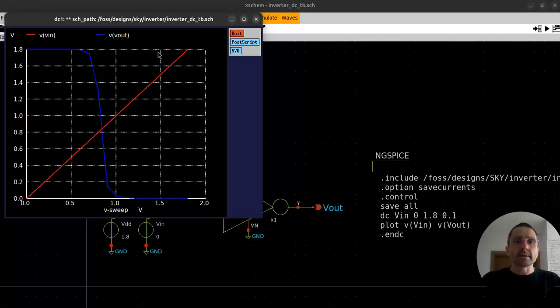And we were able to simulate this new netlist, although there was an issue, because the pins had not been matched between the test bench we had set up and the netlist. So we need to compare and check every time if the pins are equivalent. They need to be equivalent.